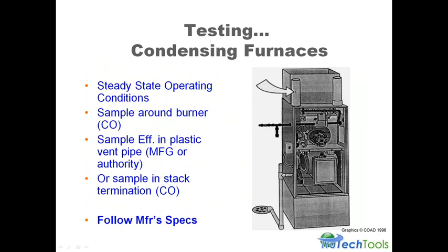So that's typically what I'll do, and that way I have a sealed plug when I'm done, and then I can take that plug out, put my combustion analyzer in, do my testing, put the plug back in, and I have a sealed flue pipe. Okay. Typically, we always recommend you check with the local jurisdiction having authority on how they want that done. And basically, that's a cop-out by us telling you that. I'll tell you the way I do it, but your building department may want you to do it another way.